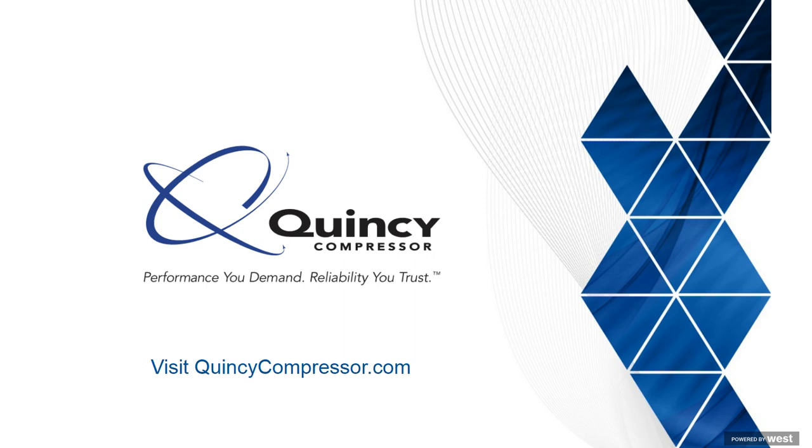That's the biggest difference between old ISO 1217 and the new DOE regulation, is that you're using very accurate raw data with no adjustments allowed. It makes the published value more repeatable, more accurate. So if you're measuring your actual machine performance, you will get a very accurate isentropic efficiency, which is also what you'll get when it's DOE compliant.